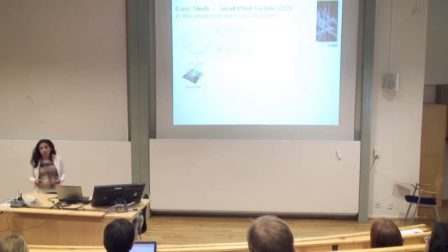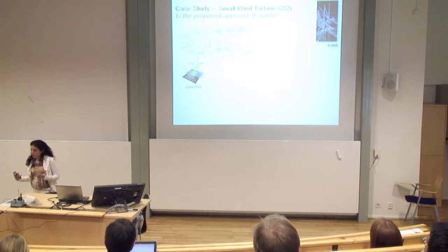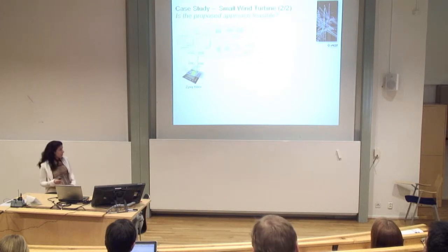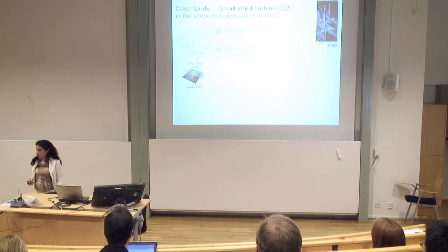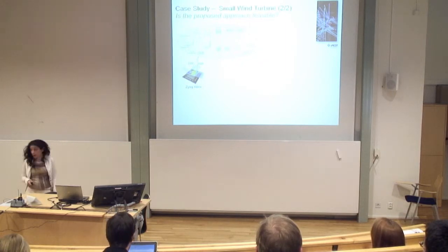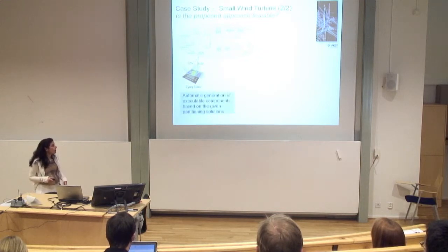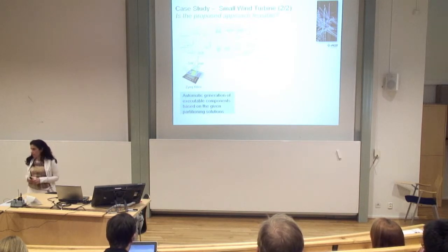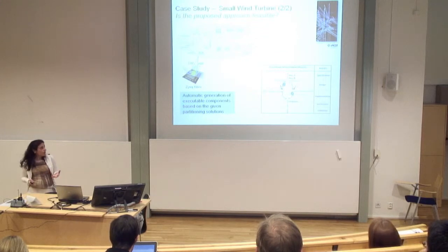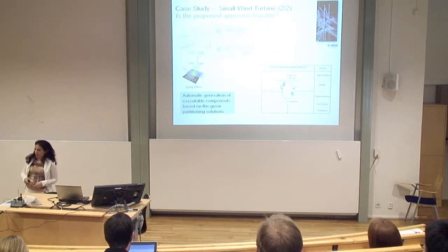We actually show that the approach with our solution, the partitioning solution we achieve and we get out from applying multicriterial decision analysis method is feasible. And basically we run the partitioning solution on a Zynq platform, basically as hardware components of two components. We automatically generate executable code to be downloaded based on the tool chain that we have seen before. So basically we can just close the loop on what we have seen.